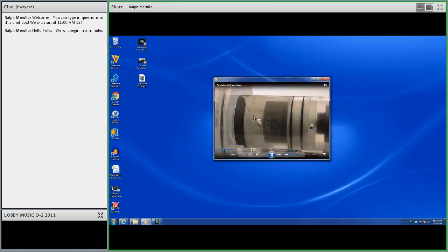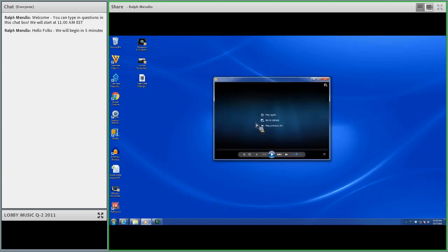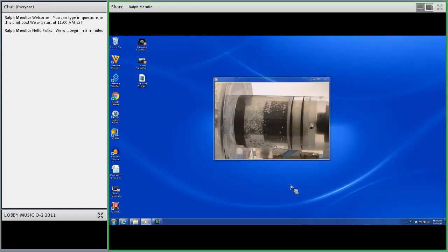So this is an example of an active throat bushing mounted inside a pump. We have the mechanical seal to the right of the screen, and we have solids, and these are settling solids. Think of grit; even some sludges will settle out of solution. That's why they have separators and clarifiers. The density of the solids allows them to separate from the fluid by gravity. What these folks have figured out is that the shaft, as it rotates in the fluid, will cause the fluid to rotate. Not at the same speed, but it's still going to rotate in the seal chamber.